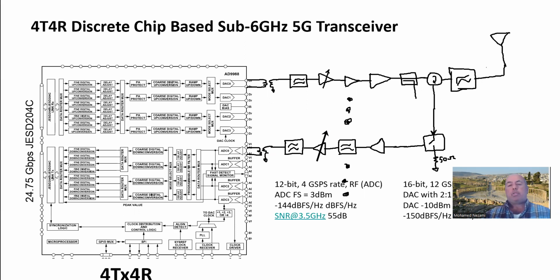Now, you start out knowing the signal to noise ratio of the ADC, and then the full scale, you back off with a certain margin, and then you go down to the quantization level, and you try to set this point here somewhere, usually say minus 20 dBm. Usually the full scale signal for this ADC basically saturates at around 0 dBm.